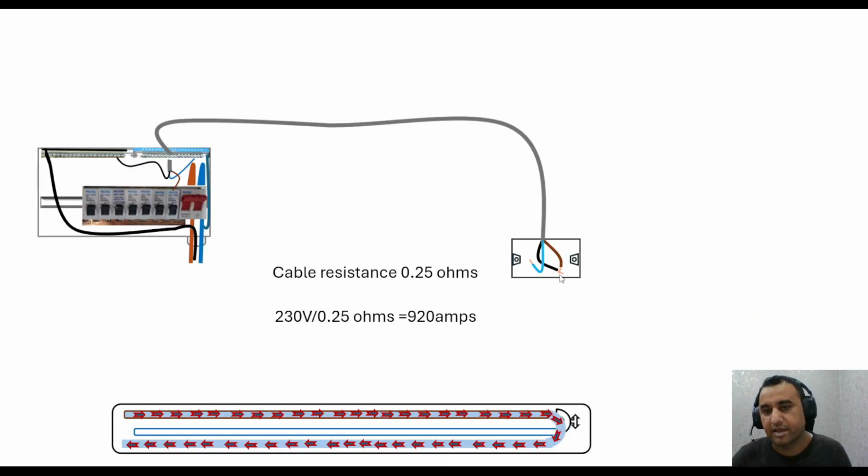It's just before the plug. There is an earth fault because this cable is in contact with the earth cable, so the current is coming from this MCB, and instead of going back through the neutral, it is going back through the earth to the system here.